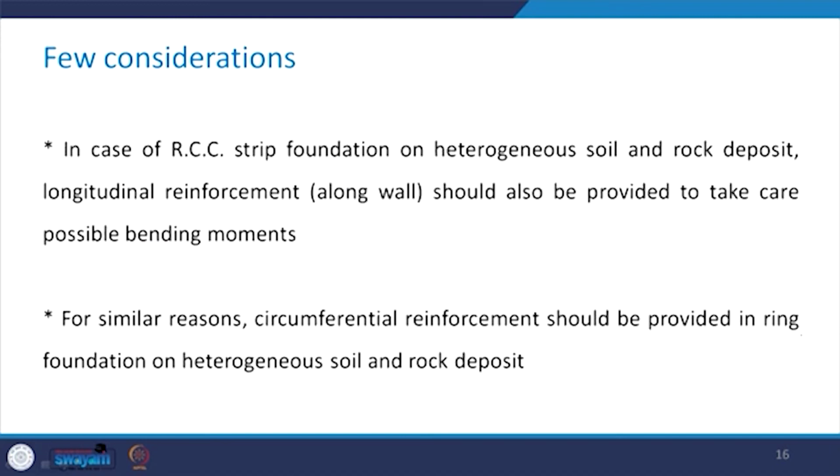In case of the RCC strip foundation on heterogeneous soil and rock deposit, the longitudinal reinforcement, that means along the wall, should also be provided in order to take care of any possible bending moments. Now, for similar reasons, circumferential reinforcements should be provided in ring foundation on heterogeneous soil and rock deposit.